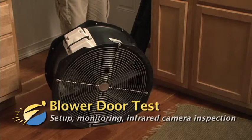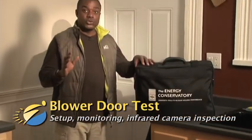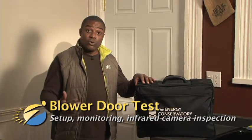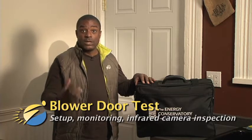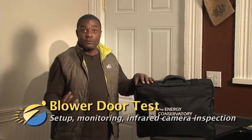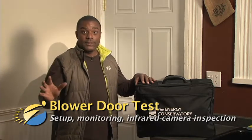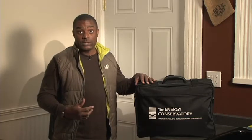Now it's time for our blower door test. But before we do anything, we need to make sure that our water heater and furnace cannot fire. That's important because our blower door creates a negative pressure inside the house that draws air down the flue pipe that can cause the flame in the furnace to roll out of the cabinet and create a fire danger. We can also pull dangerous carbon monoxide into the house, putting ourselves and the homeowner at risk.